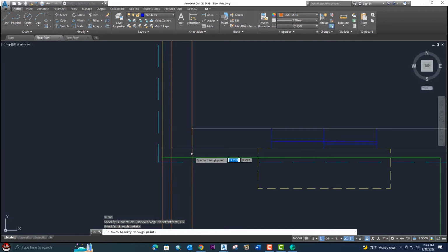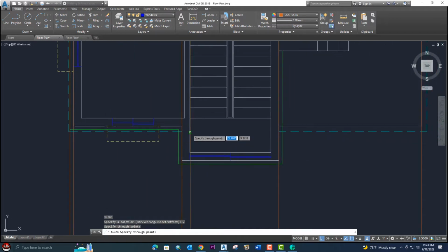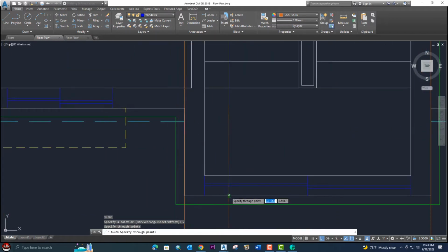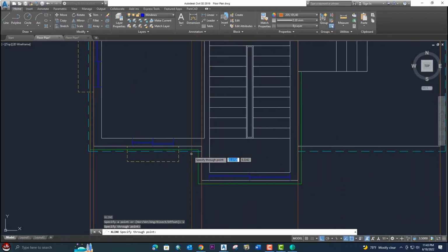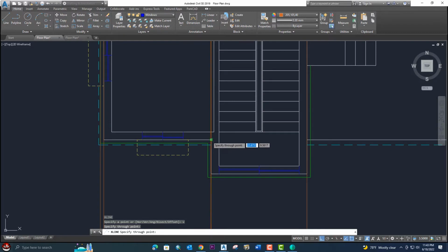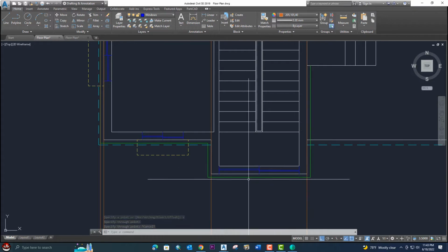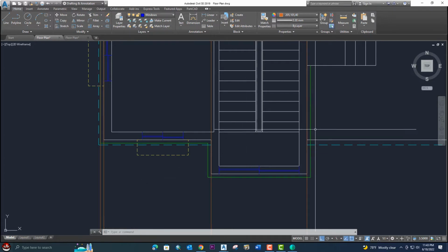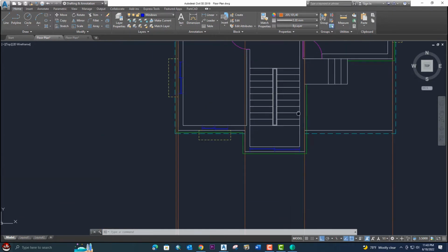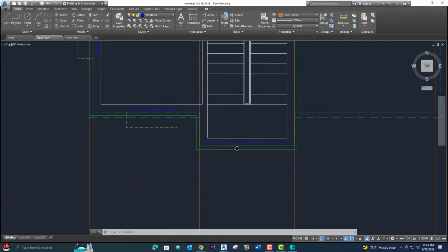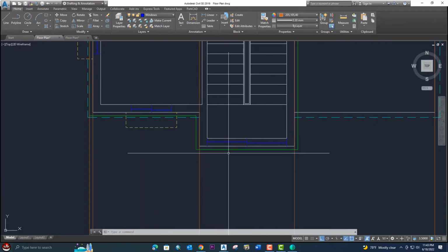This projection and plinth projection, we also need this. And remember that in the plan we forgot to design our plinth projection around this outer window. So you can easily just draw a polyline. From the polyline you can take a 0.10 meter offset, so that you can draw this remaining section of plinth.